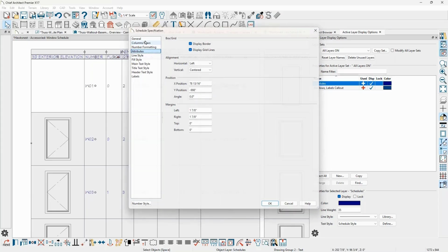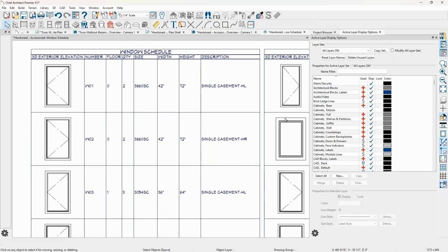One of the complaints I've had is that my text is unreadable in the schedules if I'm trying to fit the schedule into a plan or into a layout. And when you go ahead and increase the schedule text, then it blows the box up. I mean, one way to rectify that is to eliminate the 3D views, but I like to include the 3D views so it's easier to identify what the product is. Does that make sense?